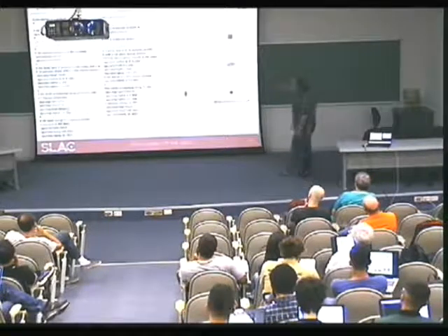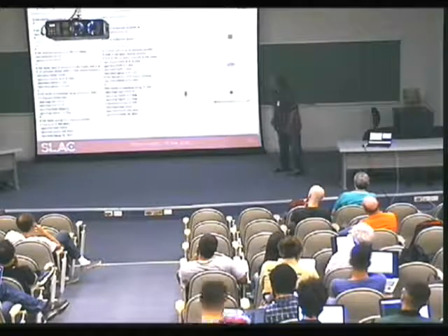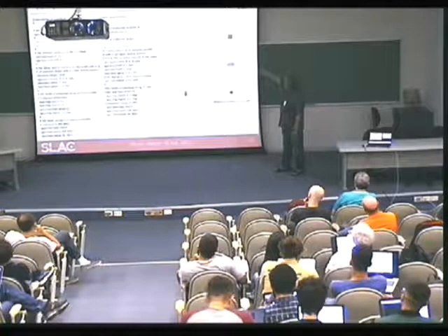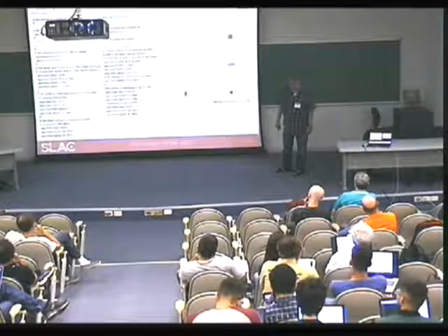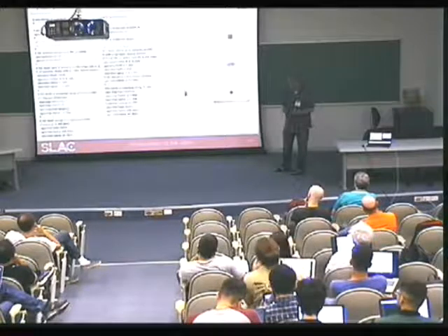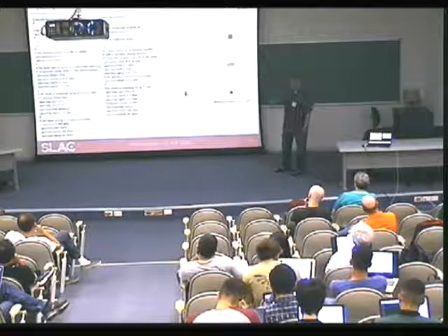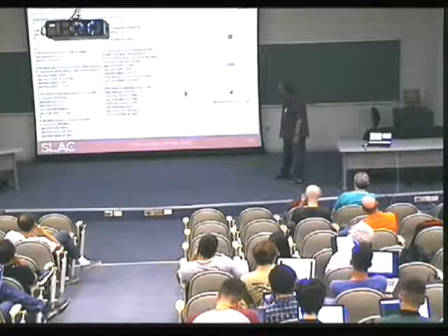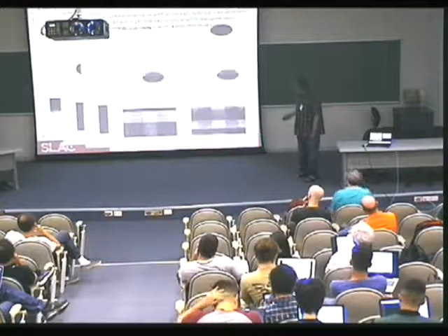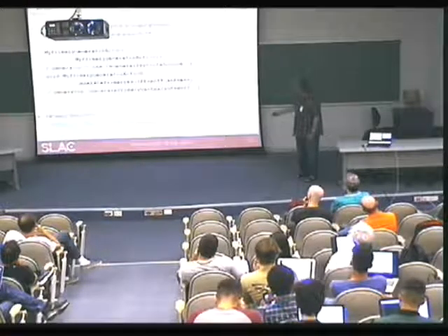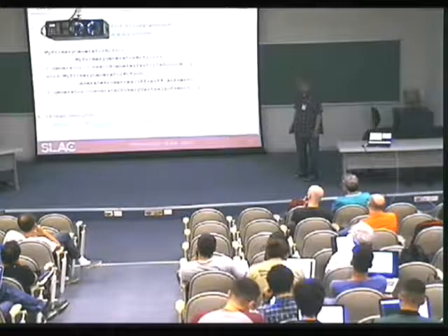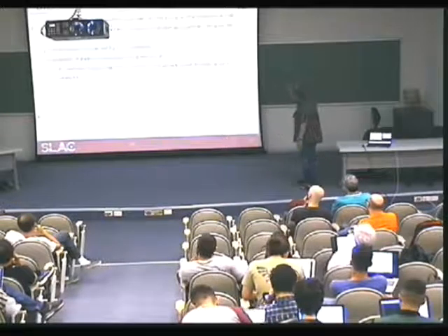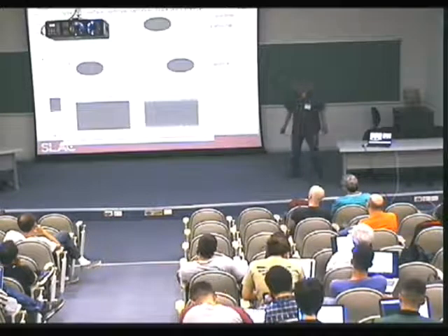For example, to specify this kind of energy distribution, you set the height of each bin of the histogram. Then the general particle source will randomize the distribution along your histogram. So it's really, really powerful. But you have to go through this link to find more than 1,000 UI commands, and you have to understand them. To be honest, I've never used it.